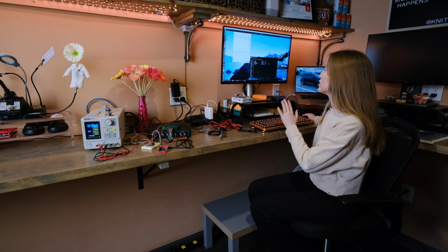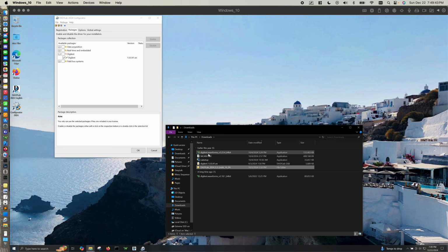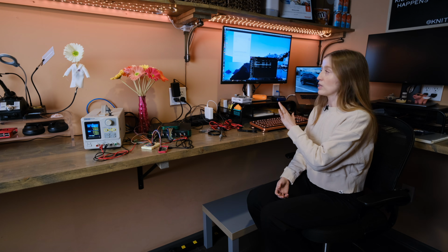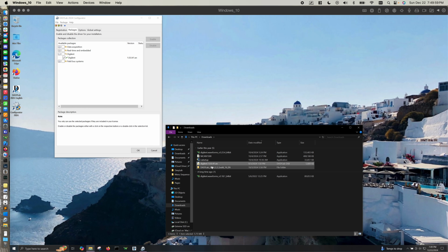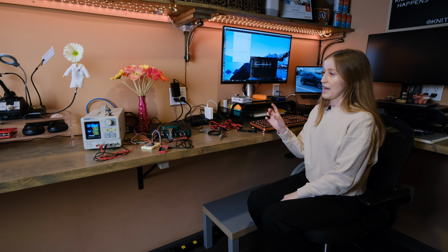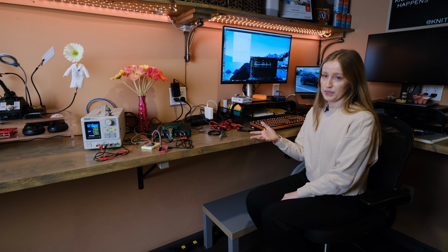For Digilent specifically, there's also this package to add the hooks in the configurator for it. The Digilent packages in DASYLab are currently still in their beta form, so that's why this Digilent enable file is required. If you run this to launch the DASYLab configurator from, that's what actually adds the hooks to recognize WaveForms is there.